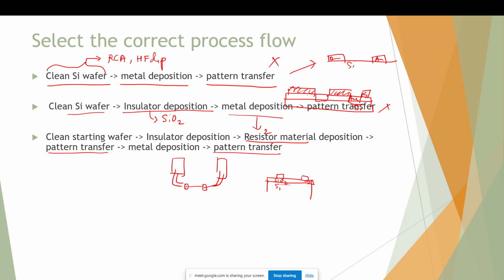So that will create a short. The general practice in such situations is to put another insulator layer. It might happen that you have some resistors here, here, here. Now contacts want to go from here to here. Then it might overlap with the resistor at this place, and that will create a short. So the general practice is to put the contacts in a different layer. They're already in a different layer, but put an insulator in between. So that part we skipped here.